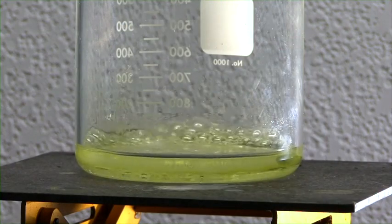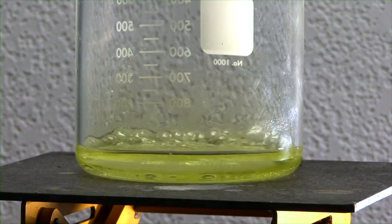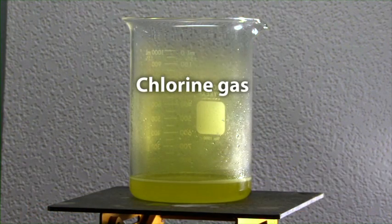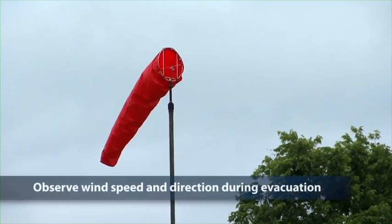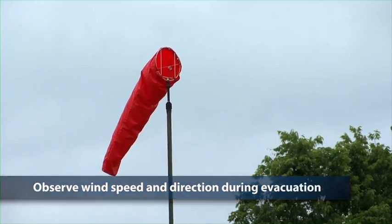If sodium hypochlorite comes into contact with a strong acid, it decomposes rapidly, giving off dangerous chlorine gas. Chlorine vapors have a sharp, pungent odor and can severely irritate the eyes, throat, and lungs. Depending on the concentration of chlorine vapor and the length of exposure, more serious injury may result, even death. In the event of a chlorine gas release or similar emergency, evacuate the area and activate your site's emergency response plan.